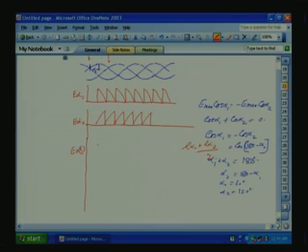If you do that, the ripple voltage will be approximately like this. It will go this way with respect to a DC value, so you can draw it. See here, there is a ripple on the DC. This ripple will be the ripple current, and this ripple voltage will be controlled by the armature inductance of the machine.